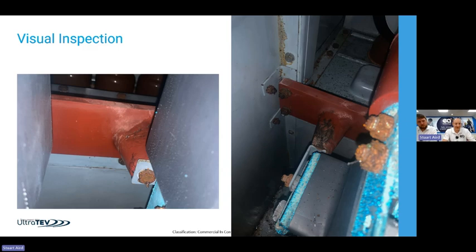So if you've got this type of equipment, any air insulated switchgear really, in a high humid environment, you will start to get partial discharge activity. It will increase it, as it reduces the dielectric strength of your air. You start getting dew points on it and things like that. So that leads us into another case study where we're talking about the effects of humidity. Well, Gareth's going to talk about the effects of humidity.